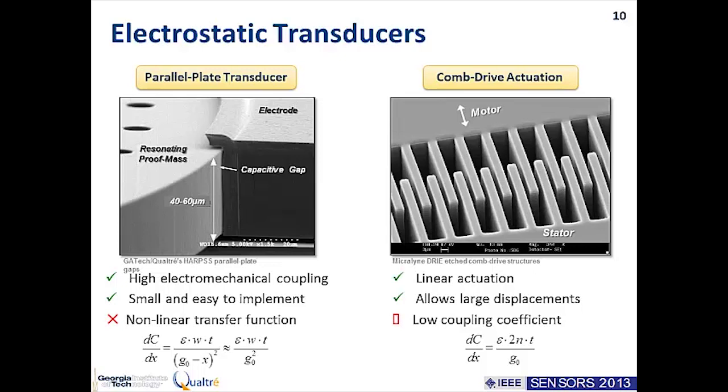And in terms of the electrostatic transducers, we can either utilize them as a parallel plate type of device in which the deformation happens perpendicular to that plate, and the advantage of measuring changes in capacitance this way is that this particular change per unit change of gap is inversely proportional to the initial gap you have squared. So what this is telling us is that as we reduce our gap size, we get a much better change in capacitance per unit of deflection.